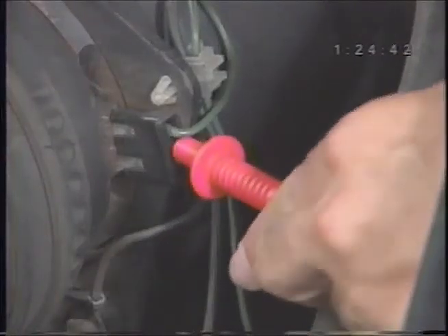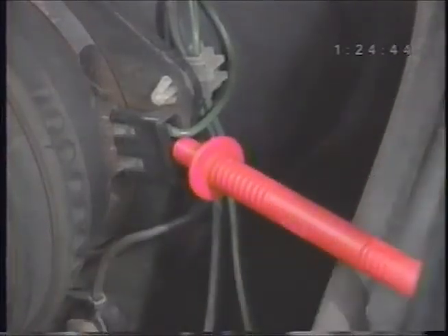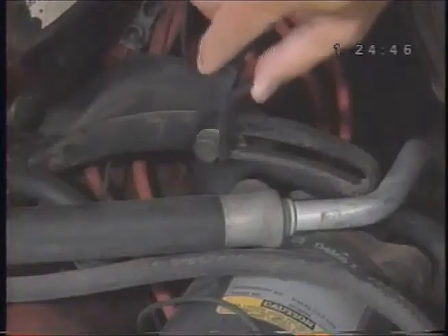One of the most common and most often overlooked electrical noise suppression devices is the clamping diode in the AC compressor electrical connector. In this exercise, you'll learn how to use Scopemeter to capture the voltage spike developed when a compressor clutch with a bad or missing diode de-energizes. Connect the channel A probe to the positive side of the connector. Connect the ground lead to a good vehicle ground.